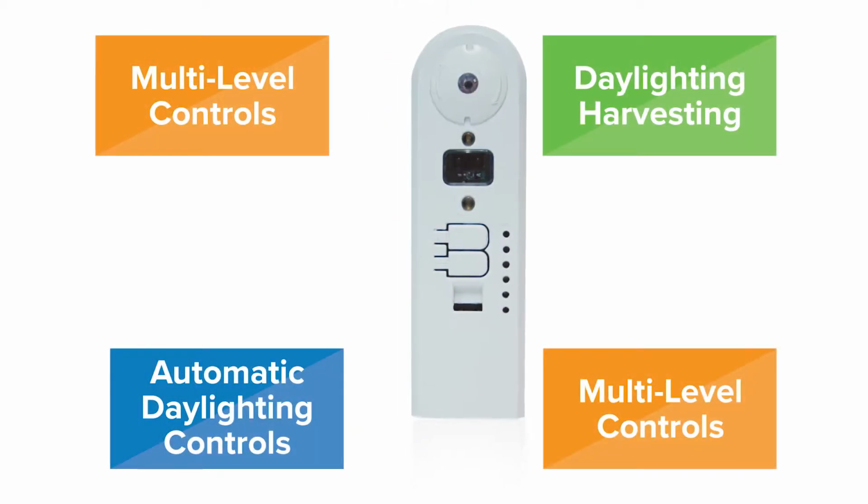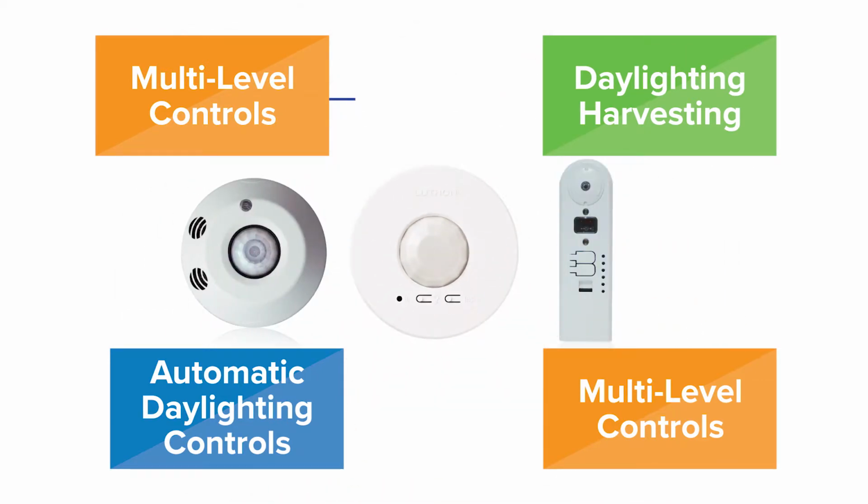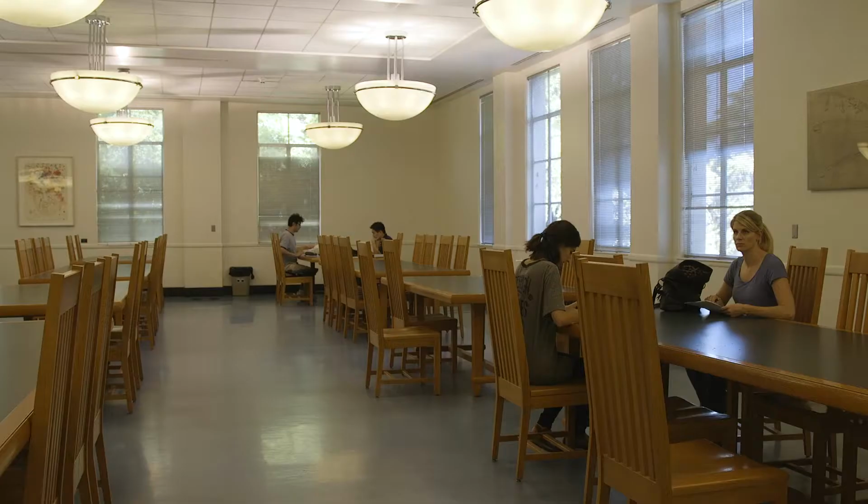Multi-level lighting controls can also facilitate other automated lighting control strategies. For example, multi-level lighting controls are key for daylight harvesting. Automatic daylighting controls utilize multi-level lighting controls to provide the necessary control steps required under the Energy Standards, either through stepped or continuous dimming. Another example is scheduling.